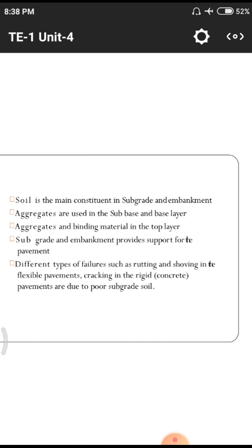They need to dissipate the total force from the train wheels to the rails, rails to the sleepers, and sleepers to the ballast and the ground layer, so there are huge amounts of base course and sub base courses in railways. But in roadways, we have only pavement, base, sub base. After that, we have the embankment. So we have to focus on these four layers.